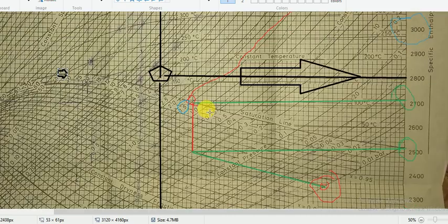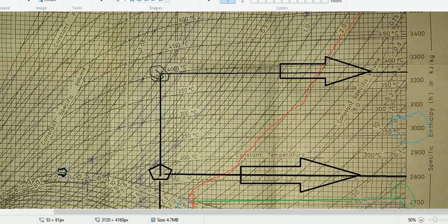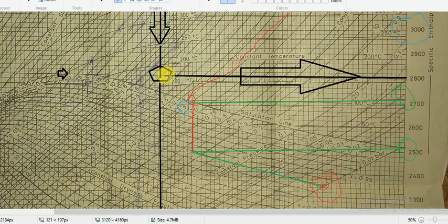Next, drop down, because it is which type of line? It is an isentropic line. So as it moves isentropically and as you move down, there is a pressure at which feed water is taken out from the turbine, that is 5 bar. If you look here, it is a 5 bar pressure. So the 5 bar pressure line meets the straight line. This is H6. Note down the value of H6, 2800.